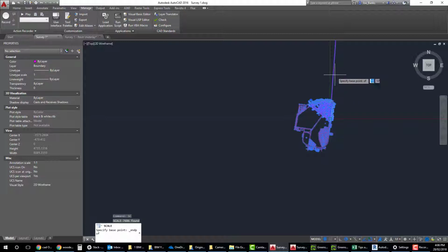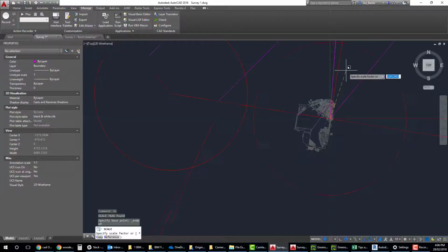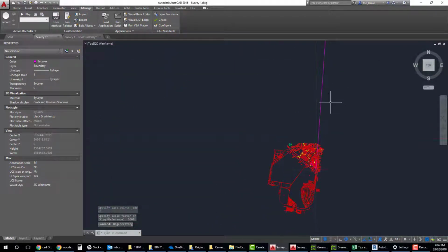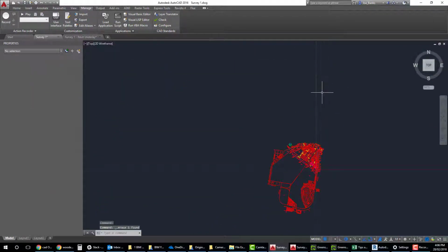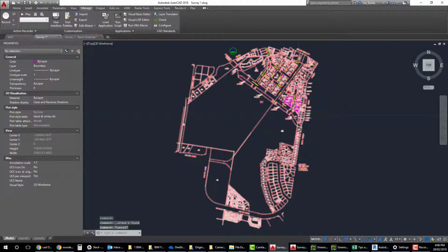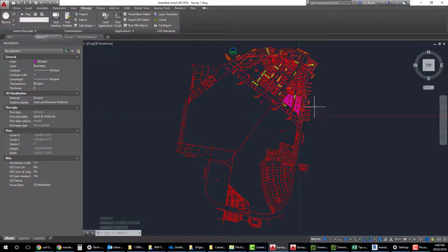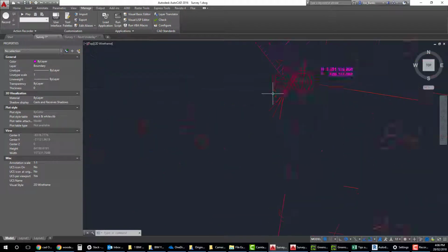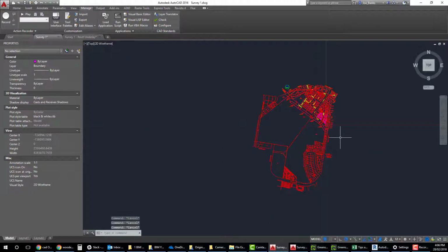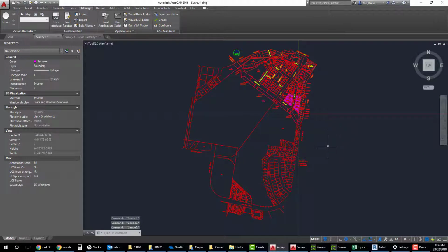Again, specify that endpoint, so we're going to use that line, and I'm going to bring this up to 1000. So now my file is in millimeters rather than meters. Now you can scale these things as you bring them into Revit, but it's much better to actually get them in a 1:1 millimeter scale in model space before you bring it in, and you won't get this weird parallax error in Revit where as you zoom in the lines jump around and move on you. So I highly recommend putting them in true millimeters in CAD rather than linking them in and scaling them on the fly. You'll get a much better result.